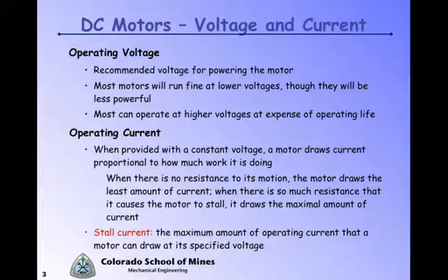So if you want to run a 3-volt motor at 6 volts, feel free to do so, but recognize that if you run it at that voltage for any considerable length of time, you'll be buying a new motor. The exact duty cycle that you could run is a matter of conjecture, and I'll leave it to the experimenter to find out. But you really should buy motors and power them according to their recommended voltages, and you'll be fine.